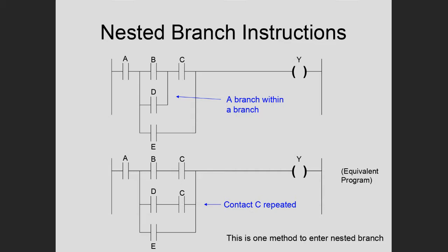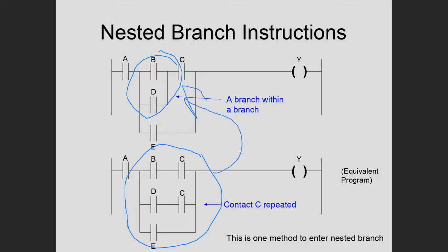And some PLCs, there's no way to implement this. So what you do is you can do this. These two circuits are logically equivalent. So if you have this, in your software, there's no way to implement this inner branch. So you can do this. This is equivalent to what's above. So I would just say mark this and remember these two are logically equivalent.